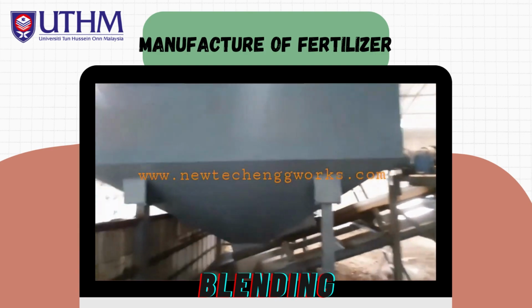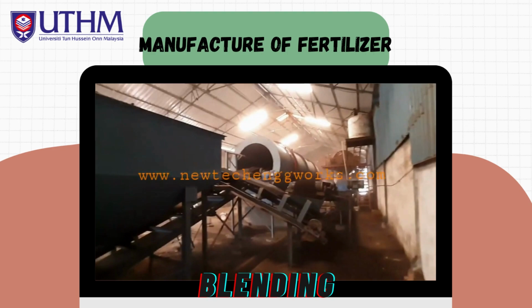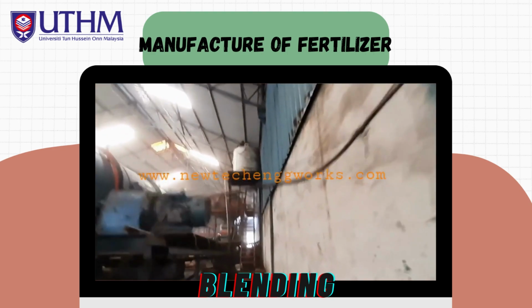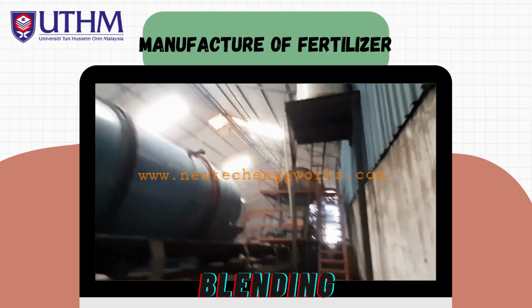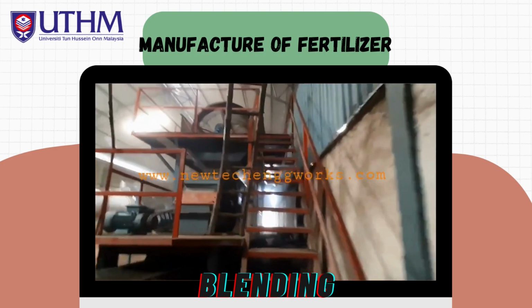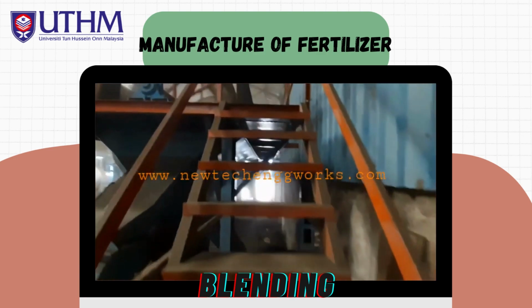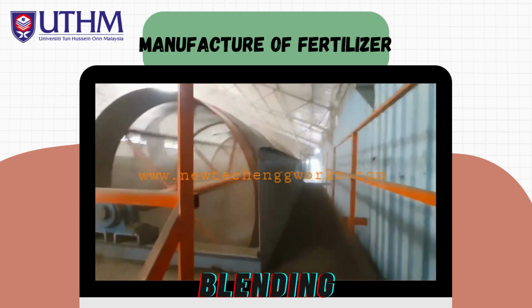After granulating, it continues with blending. In this process, the different types of particles are blended in appropriate proportion to produce a composite fertilizer. The blending is done in a large mixing drum that rotates in a specific number of turns to produce the best mixture possible. After mixing, the fertilizer is emptied onto the conveyor belt, which transports it to the bagging machine.